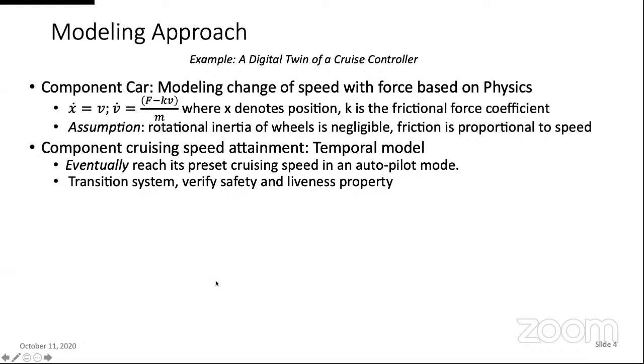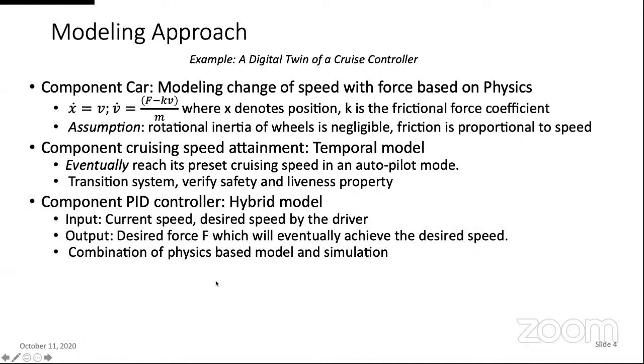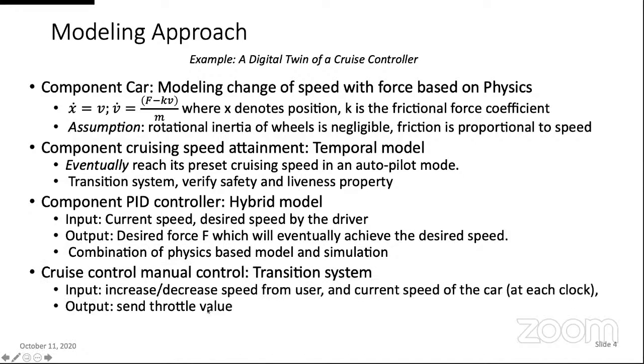Then there could be a hybrid model, where, for example, you want to build a PID controller. You are getting the current speed, which you might be getting from the real sensor, and the driver sets the desired speed, and the output is the desired force F that will eventually achieve the desired speed. In order to do this, you obviously need the physics-based model, plus you need to do simulation. Slowly things become more complicated.